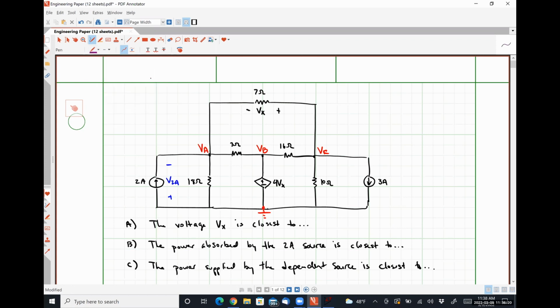So I'm going to write that like this. I dependent, applying Kirchhoff's current law at node B, is simply the current that branches off and flows to the left through the 3 ohm resistor added to the current that branches off and flows to the right through the 16 ohm resistor. Everybody okay with that analysis?